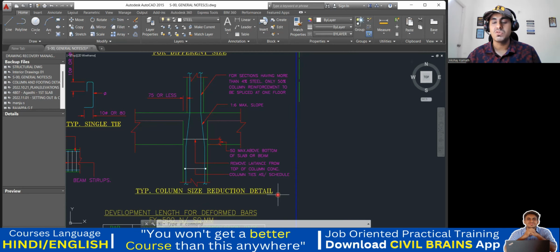Typical column size reduction. When you have such things, how do you take care of the reinforcement? He's telling us that you bring a bar from here. This is, let us say, your third floor. You bring a bar from the third floor like this. Then you need to give a small crank, or you can call it a joggle. Just bend your bar like this, and then take it straight. This is your next floor. This is your terrace portion.